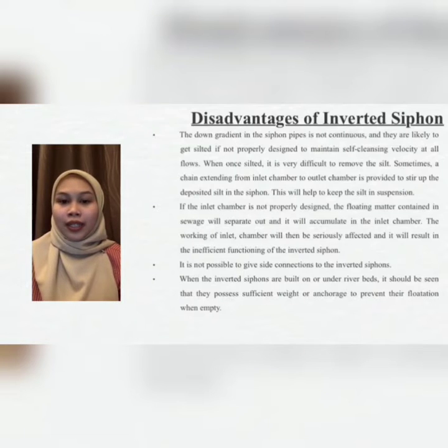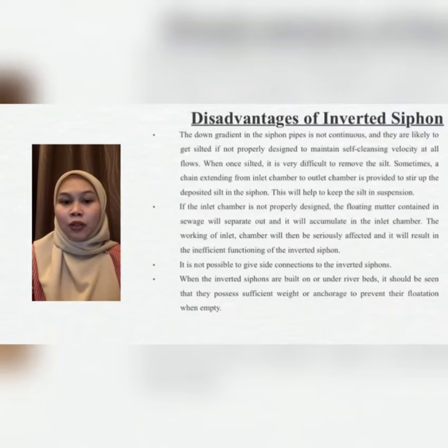Disadvantages of inverted siphon. The down gradient in the siphon pipe is not continuous and they are likely to get silted if not properly designed to maintain a safe cleansing velocity at outflow. Once silted, it is very difficult to remove the silt.